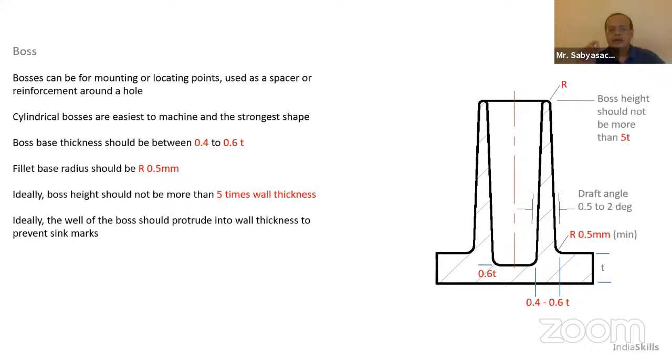So again, draft angle, extremely important. Everything has to have fillets. Plastics should not have any sharp corners, because sharp corners mean stress concentrations. Plastics are very, very susceptible to stress concentration, unlike sheet metal. Or you have cast components in any kind of alloy, in aluminum alloy. They might have, ideally not, but plastics should never have.